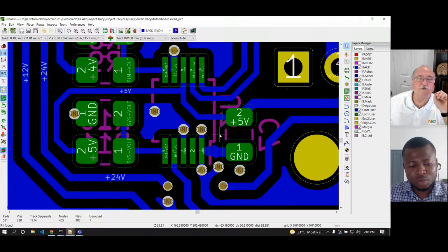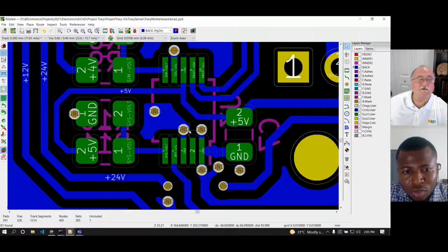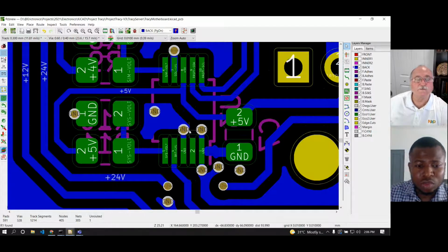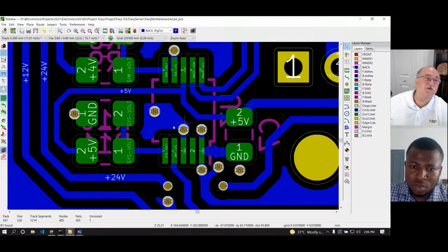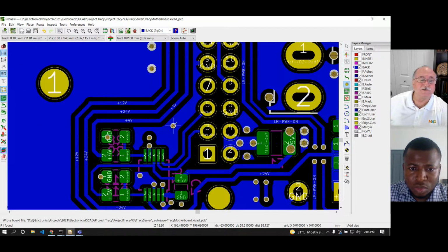Yeah, that's fine. Every additional via you place to connect the horizontal ground copper increases the density of your Faraday shield. That helps to reduce the overall radiated emissions, and reduces the conducted emissions by giving everything a better path. And from an ESD perspective, it makes your board more robust and able to withstand greater levels of ESD.